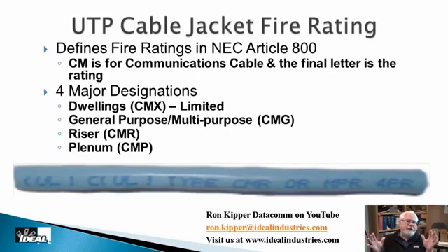And generally you can tell it's plenum because the jacketing on it that makes it plenum-rated in many cases does not hold ink very well. And you'll notice that those plenum cables, the colors are pretty faded. Blue looks a lot like green, and brown looks a lot like orange. So I can quickly tell if it's plenum, usually just by how faded the colors look.